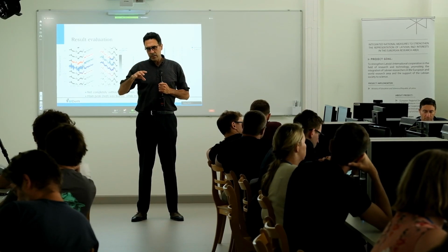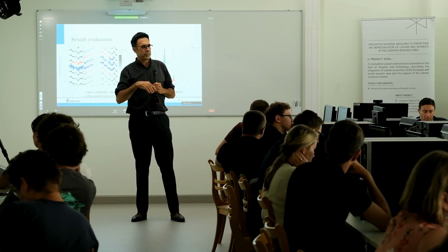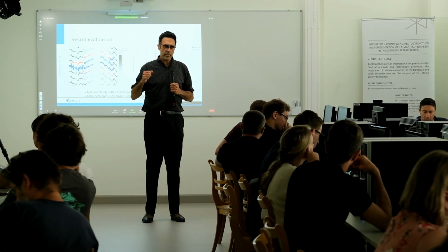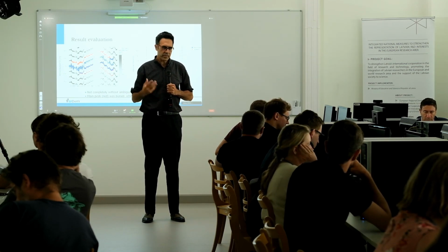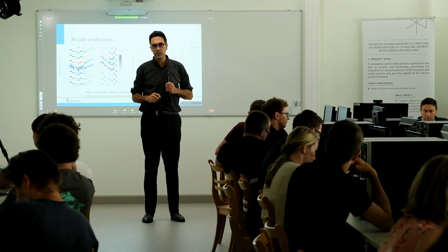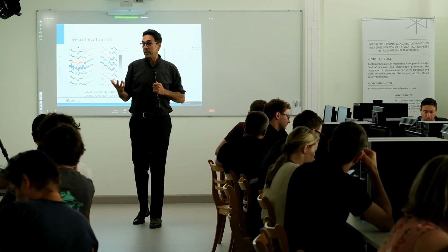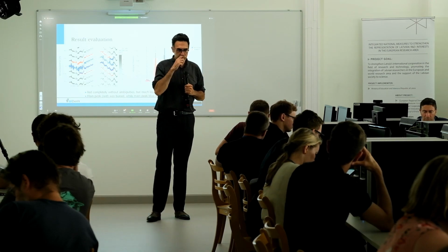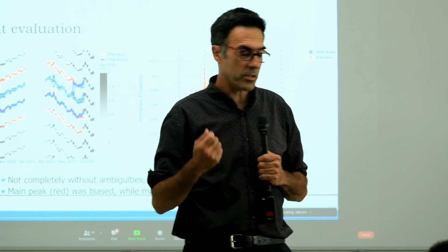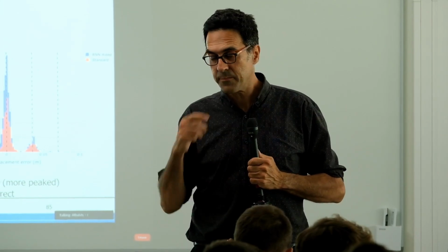And in the end, we really moved to the time series approach. I hope that I have been able to convince you that if you use hundreds of images, or 133 in this case, this enables us to really dramatically beat down these error sources like the atmosphere. And we still get about 2 million good measurements over one city, like Riga. And we have data that we can analyze. And I also hope that I've been able to show you that some of these analyses are practically meaningful, right? They can be used to monitor an asset, to plan ahead, to reduce risk.